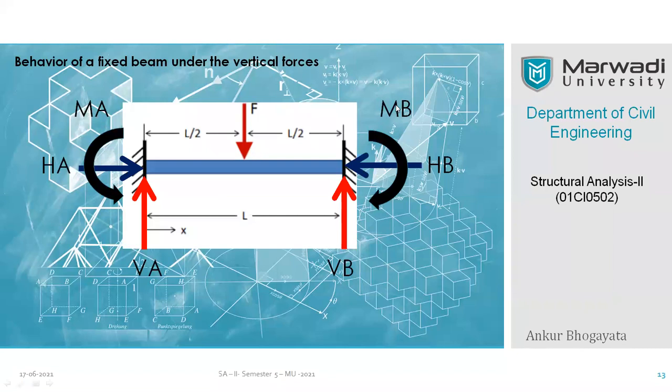Okay. So these are the primary forces, or we can say end forces, or reactive forces, developed in the fixed beam in a simple form of loading. Now, if you change the nature of the force, this reaction doesn't change. That means the nature of the reaction doesn't change. For example, instead of a point load, if I convert this point load into a UDL entirely spread over the complete length L, the end reactions will remain the same in nature. That means two reactions and one moment.